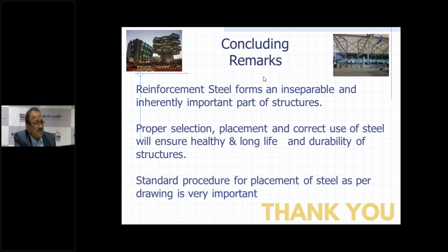Mr. Somnath is asking whether the use of corrosion resisting cement prevents corrosion of steel. Oh, this is an interesting question. Corrosion resistant cement, actually there is nothing like corrosion resistant cement. It is more of a marketing word that has been coined by a few cement companies. Actually, this corrosion resistant cement is nothing but Portland pozzolana cement.